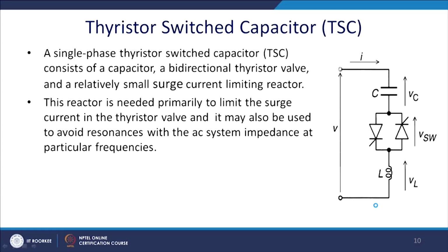Now let us see another shunt compensator, that is TSC, thyristor switched capacitor. So, the single-phase thyristor switched capacitor consists of a capacitor, a bidirectional thyristor valve, and a relatively small surge current limiting reactor.